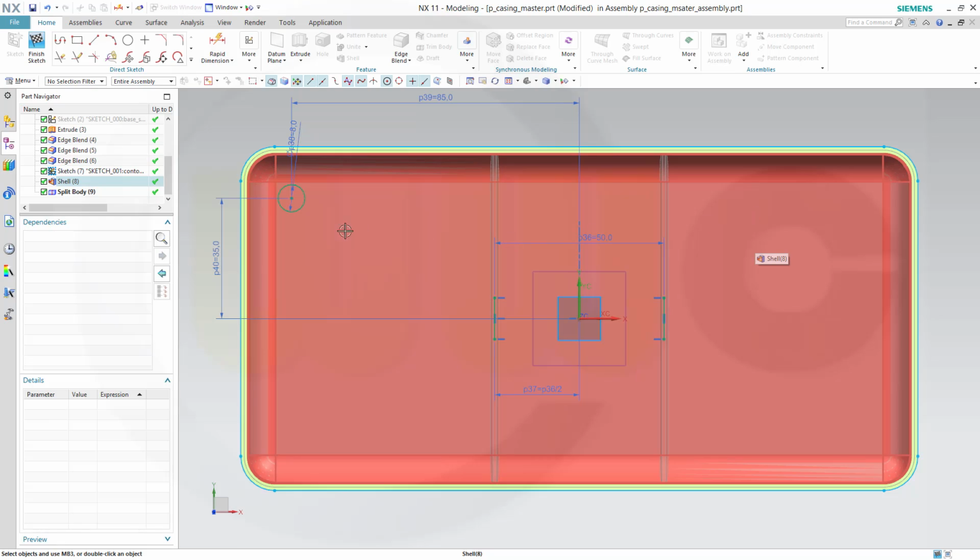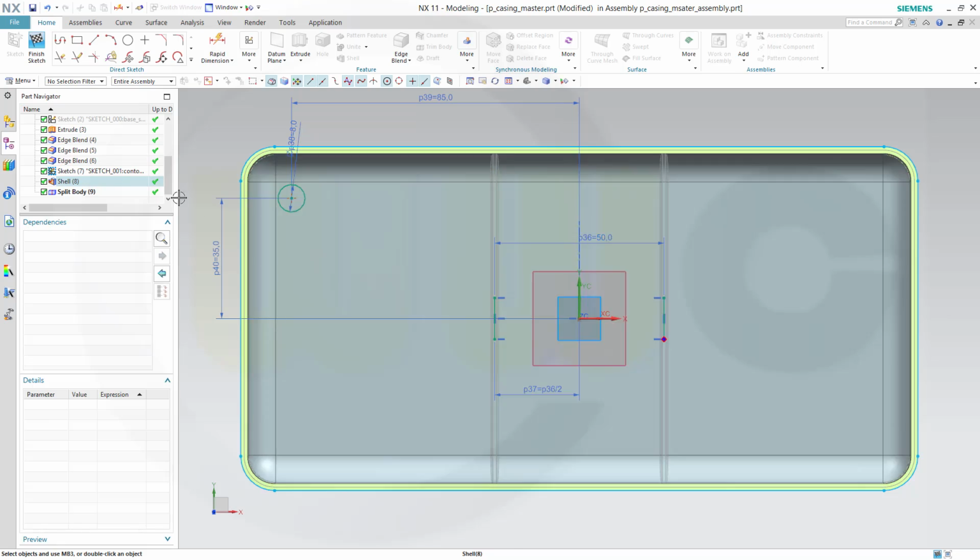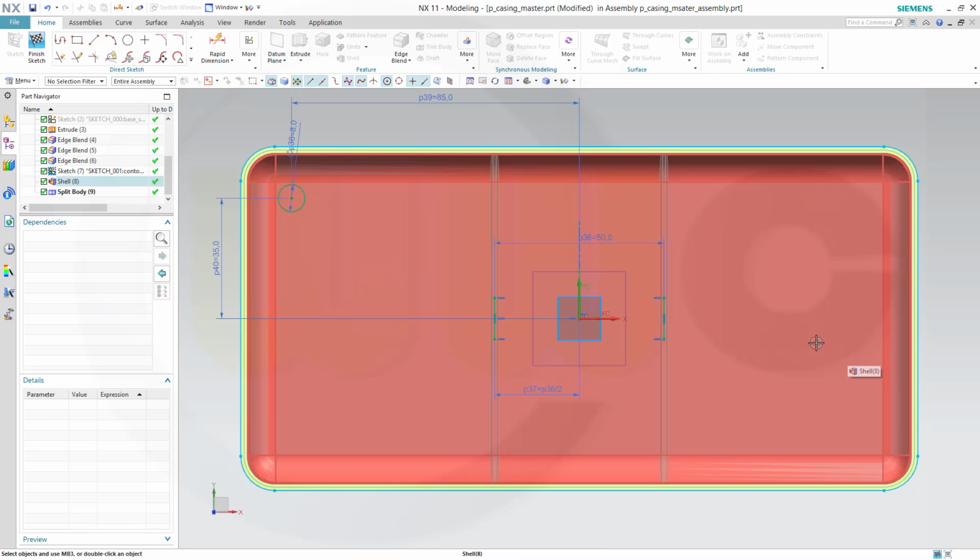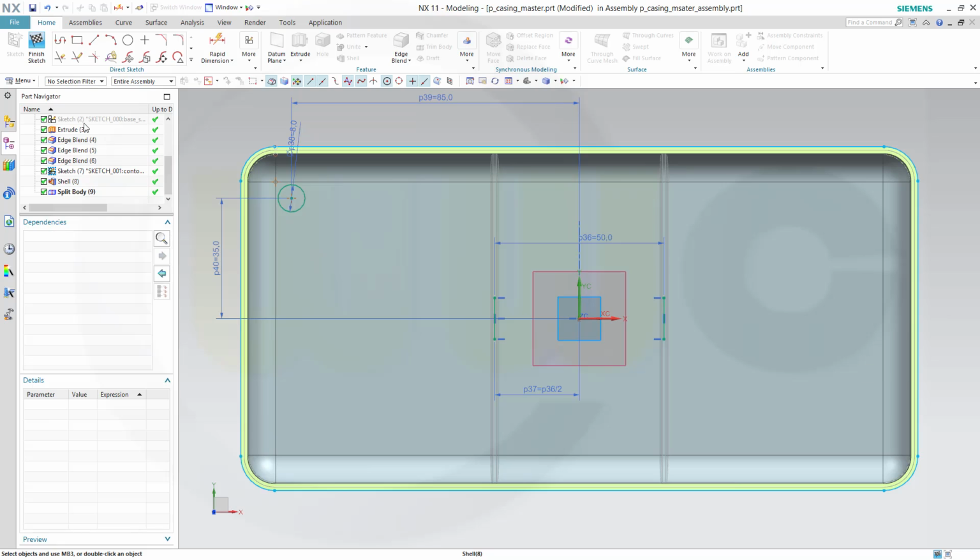Now you could do it with a pattern in the sketch or with a pattern in the parts. So if you want to control it with the master part, you would do the pattern right here, so it will do it with points, for example, just to show you different methods. I will use a point. Set it right there, then make a pattern with that point.